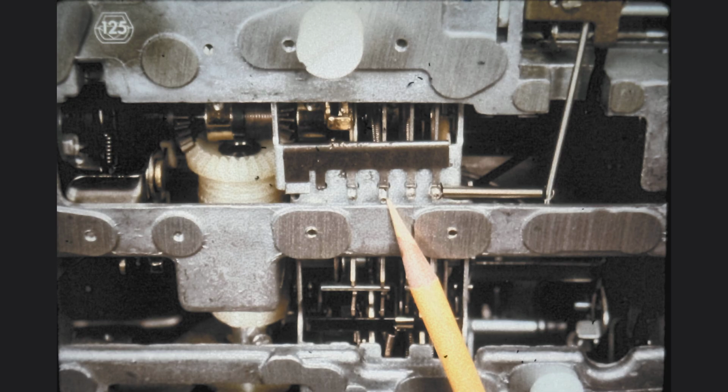In fact, on dual pitch machines, the spacebar mechanism doesn't have a selector latch either. This is why the same criteria applies. Have the adjustment screw for the spacebar interposer match the screws located in the center of the operational cage.